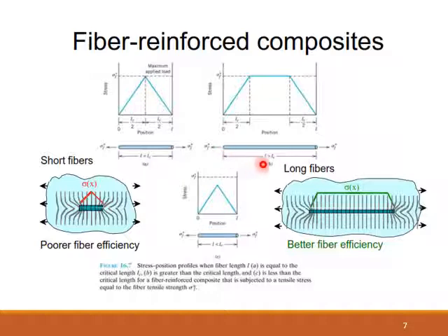But if the length of the fiber is greater than the critical length, then if you load the composite up to the strength of the fiber, it does not fail immediately. The fiber will still be functioning within the matrix without failing before it eventually fails. So you still have some time to continue to use the fiber, which will continue to take in loads without failing before it eventually fails.